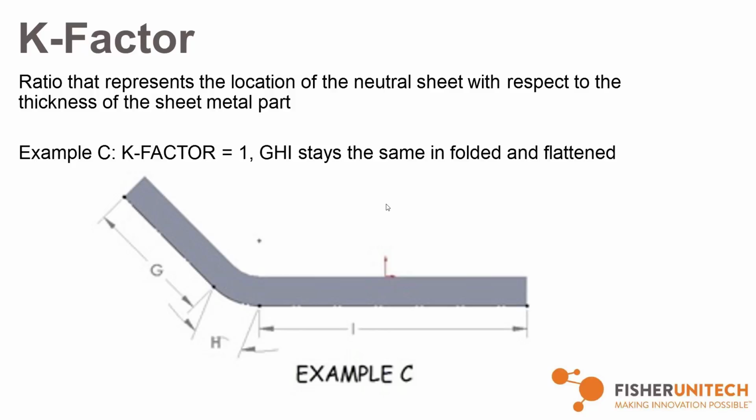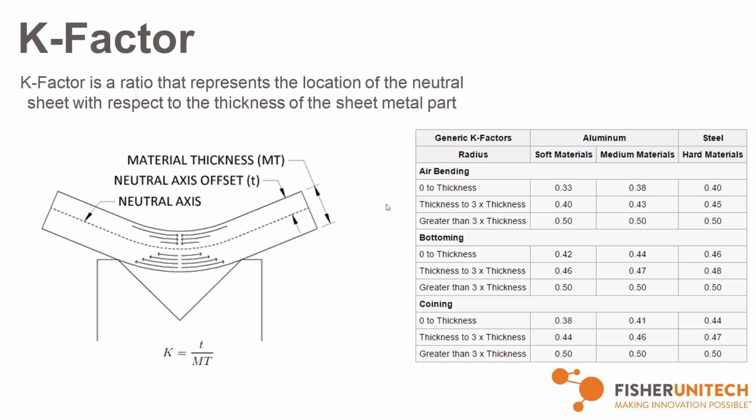Okay, great. Can I ask a question? The K factor is not going to be changing with the material thickness? To a point, yeah. It depends on the material a little bit, but if I bend 12 gauge stainless and then bend 12 gauge mild steel, the K factor will remain the same for 12 gauge, or 0.105 thickness. At least that's what we had discovered.